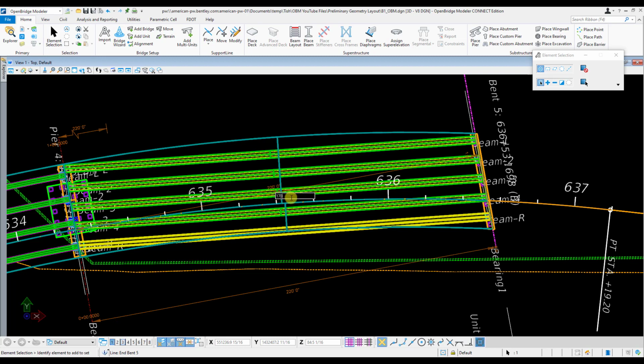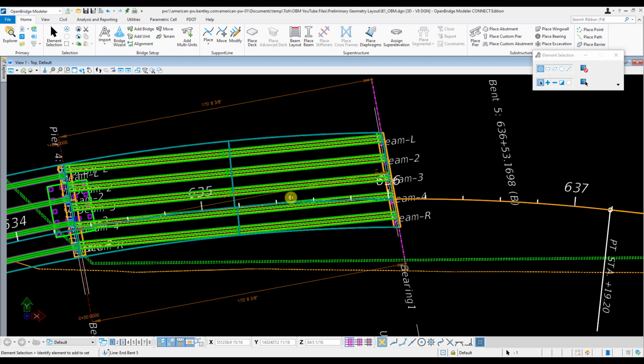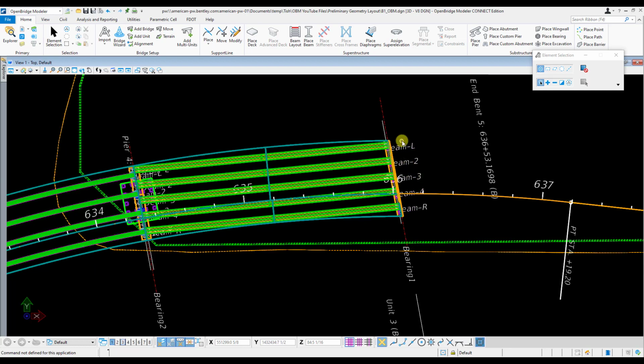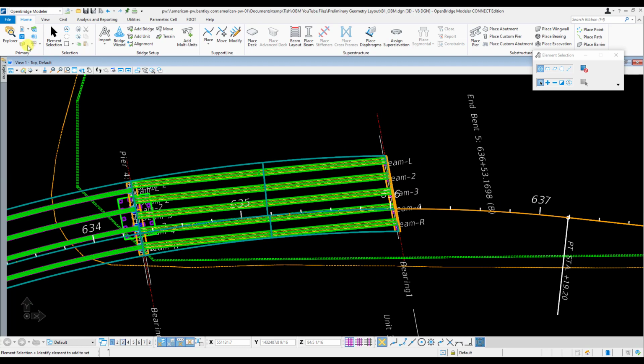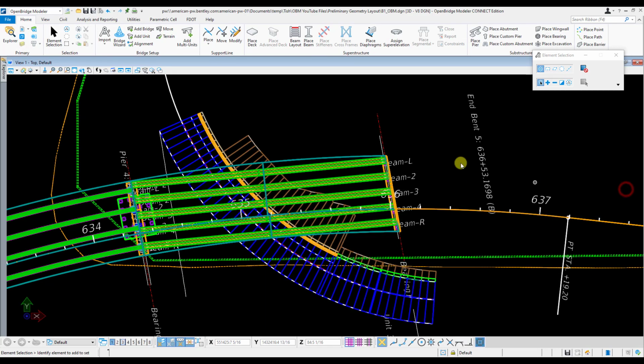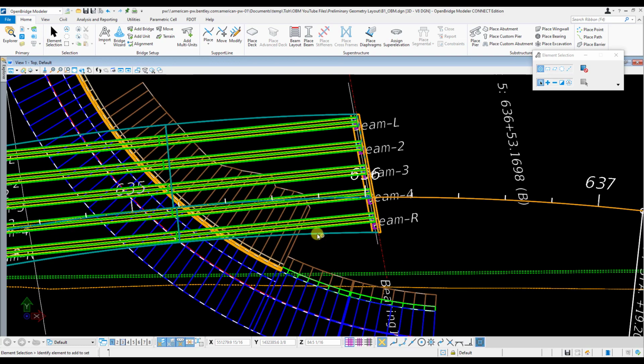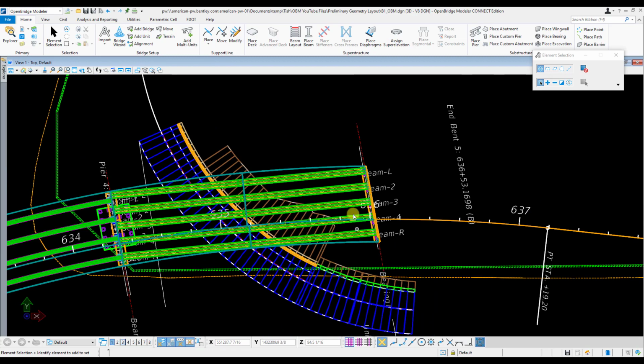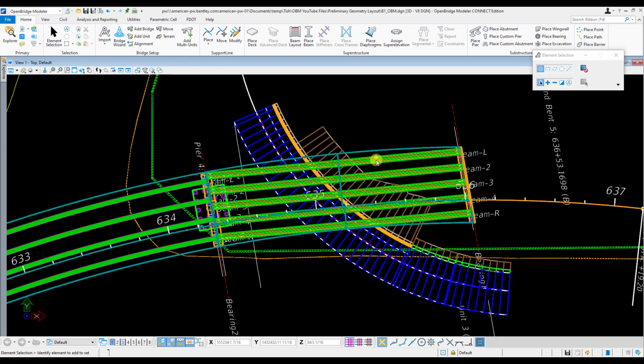$220 foot offset to begin with. Try something like 170. And we got that span shortened up. And now let's turn on that other roadway file to see how that works with the ramp there. And that's fine here. And I do know that there was a bike path that kind of came around this area right here. So I don't have that file reference in now, but this is about as short as I can make that from that bike path there.